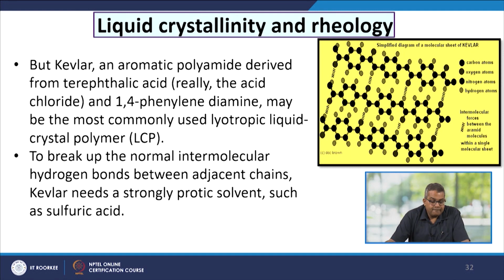But Kevlar, an aromatic polyamide derived from terephthalic acid, really the acid chloride, and 1,4-phenylene diamine, may be the most commonly used lyotropic liquid crystal polymer (LCP). To break up the normal intermolecular hydrogen bonds between adjacent chains, the Kevlar needs a strongly protic solvent such as sulfuric acid.